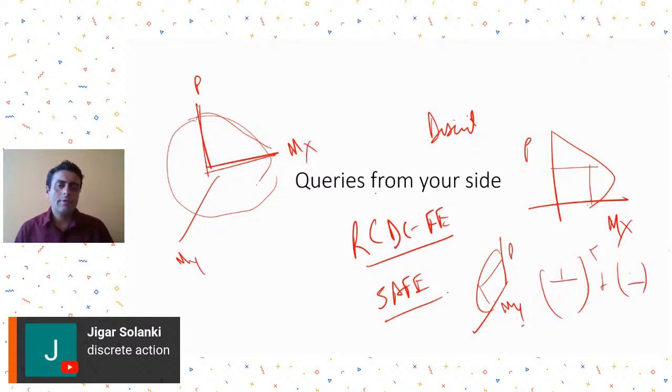In the resultant moment approach, basically I find out a resultant moment on the basis of the biaxial moments. I find out a resultant moment, and that resultant moment I directly plot on my PM interaction 3D surface. That is what we actually do.